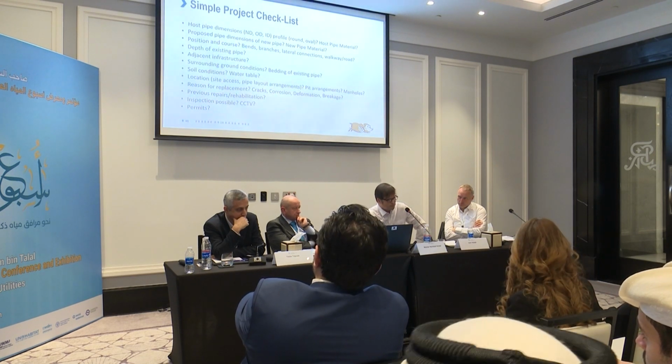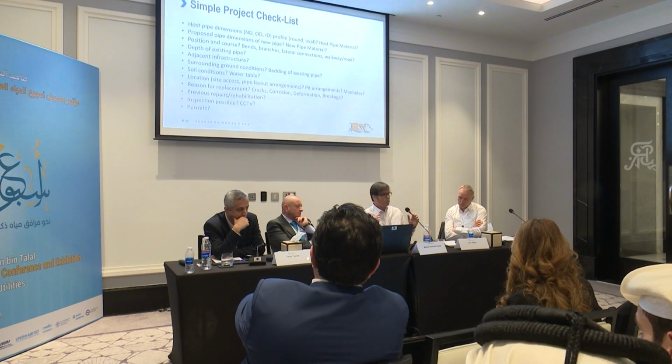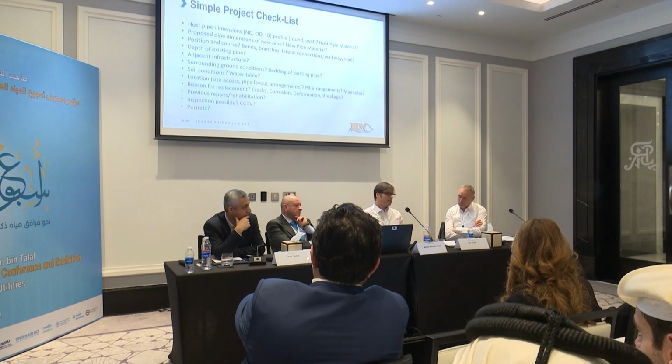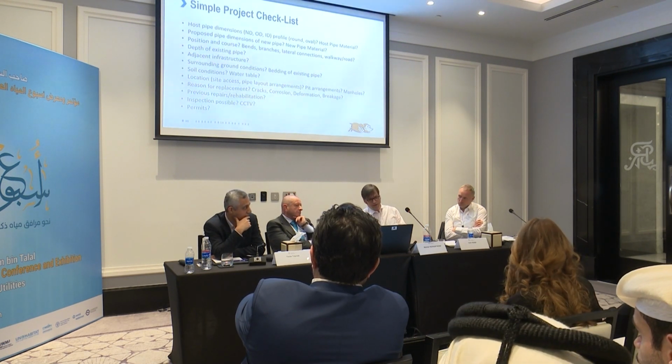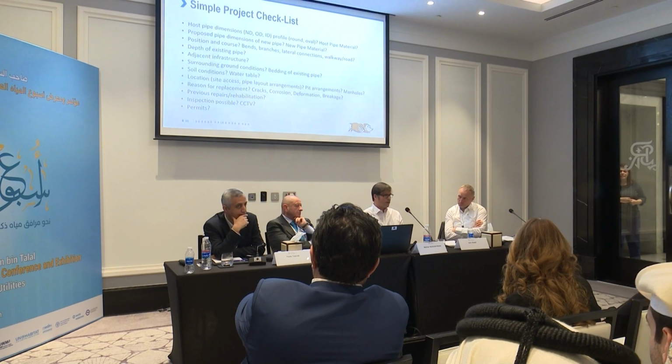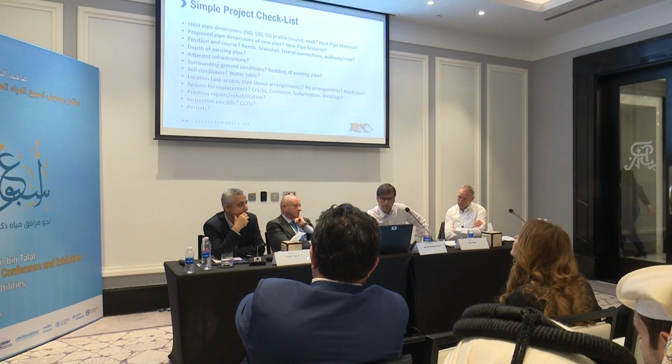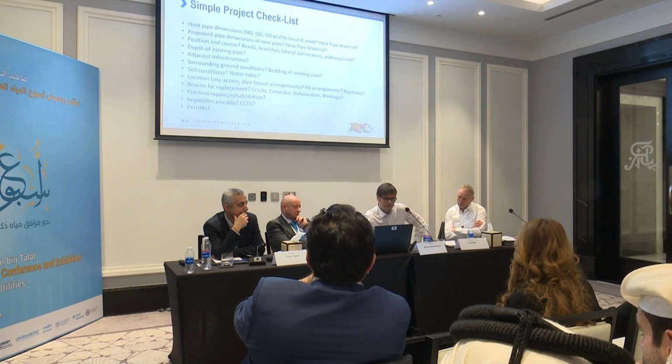So once I've determined all of this, and I've come to the point where I say pipe bursting is possible, because much like the CIPP, we cannot go around bends, we cannot do 90-degree bends, we can do a little bit of directional variation, but we like things best when they're in a straight line. Once I've determined that pipe bursting is possible, then the vast majority of jobs are actually carried out using a process called static pipe bursting.